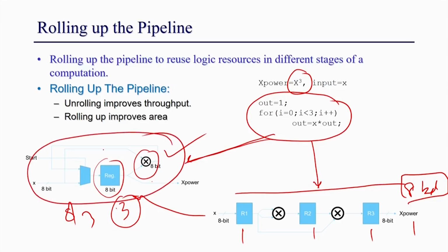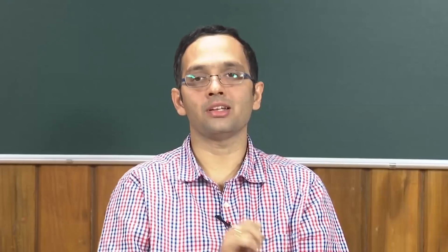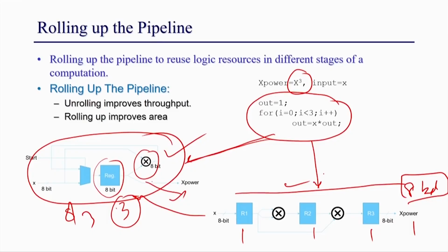Okay. So, this is what is called pipelining. If you have a pipeline design and really care about your area, your design is very big, and even saving these 2 multipliers is useful, you can probably do this implementation instead of this, right. But again, if you do this, you need some other synchronization like a finish signal, because now it will take 3 cycles. So, you will generate a finish signal to synchronize with the other components. Okay. So, it is your choice: if area is a very crucial factor, you will choose this, and if throughput is important, you will choose this one.